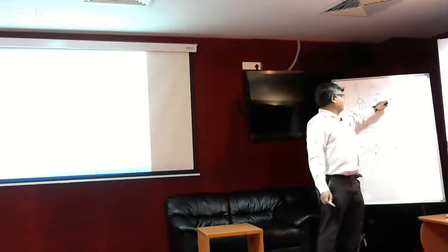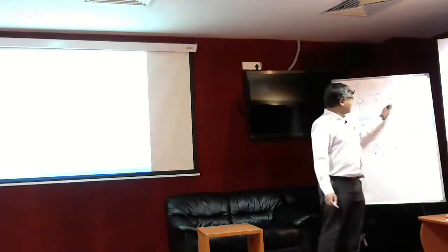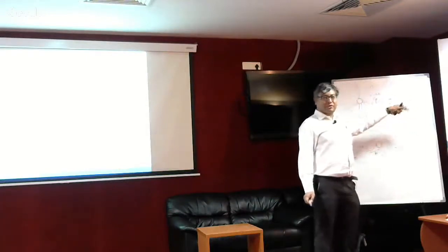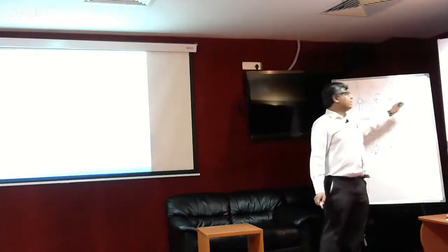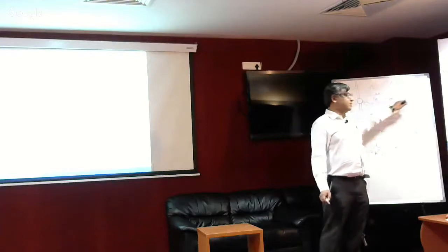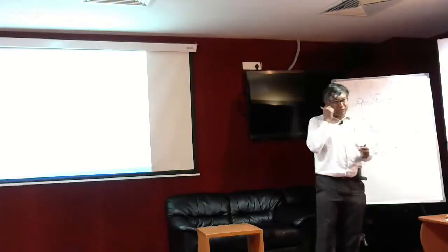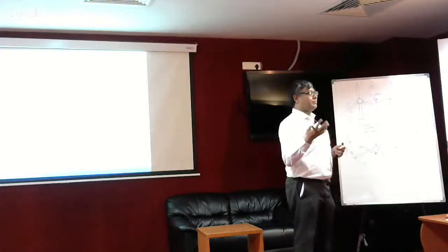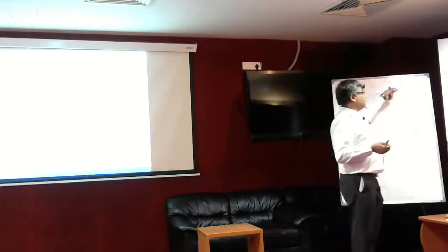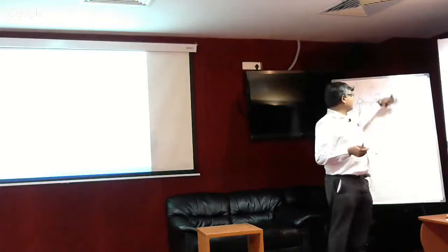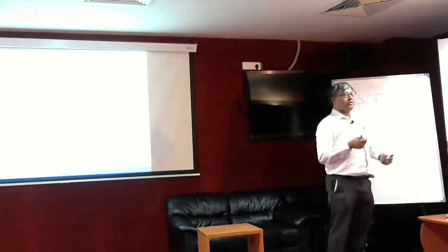Okay. Then because it traverses a longer path, but at the same time they have to meet at the same point because of no separation, that means the velocity here will have to be higher than this part at the bottom. If the velocity is higher, then if you apply Bernoulli's principle, you have the pressure gradient term and V square over 2g. Obviously where you have a higher velocity, the pressure has to go down. So the pressure is lower here and higher at the bottom, and that is actually causing differential pressure.